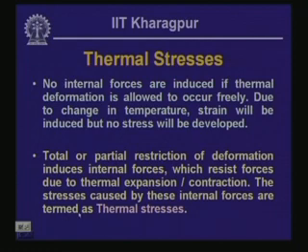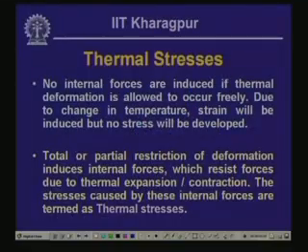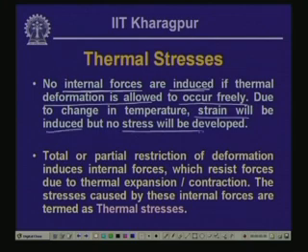Now, if thermal deformation occurs, as I was telling you, and it is allowed to move freely, then there is no possibility of inducing any stress in the member. No internal forces are induced if thermal deformation is allowed to occur freely. There will be strain induced, but there will not be any stress in the member, as no internal forces are getting developed.